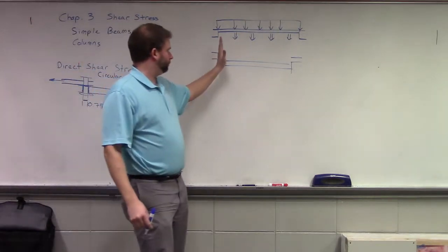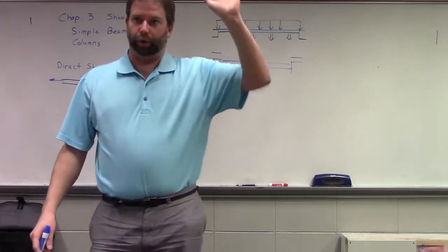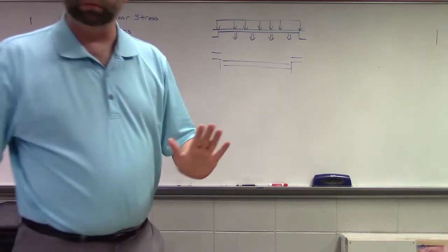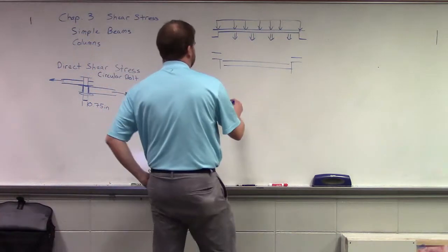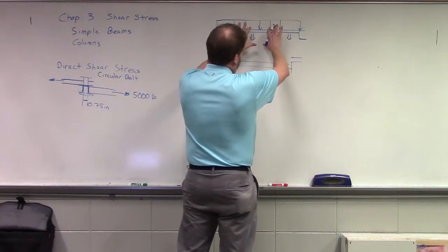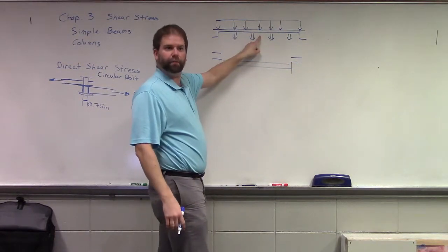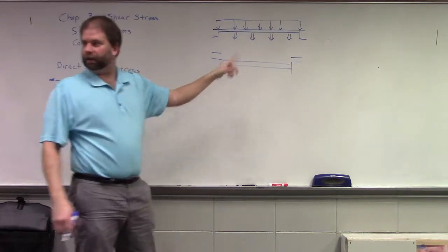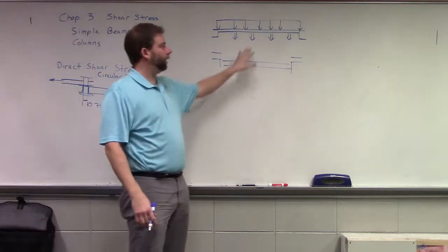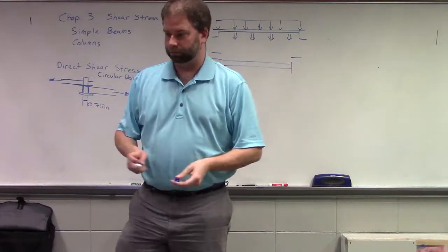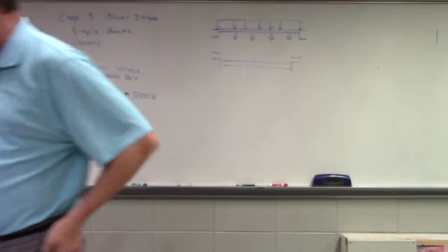The definition of shear is when you've pushed through that entire cross section. If we instead are deflecting and have an increased deflection through the middle of the beam, and we're getting failure in that tension face, that's bending, okay? So, just be aware of that.